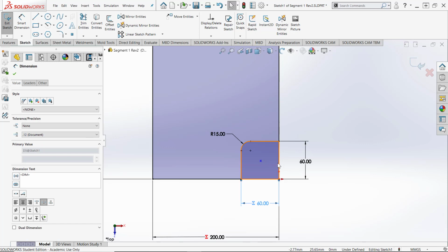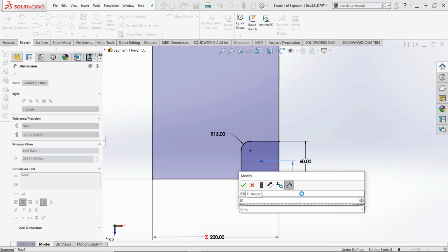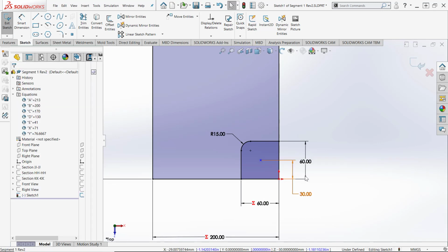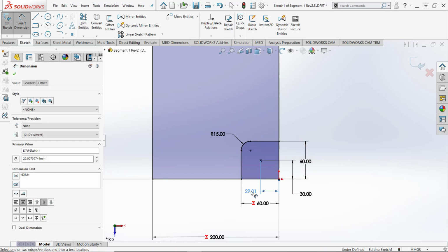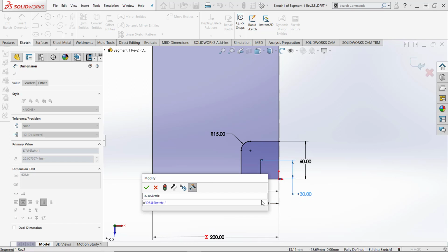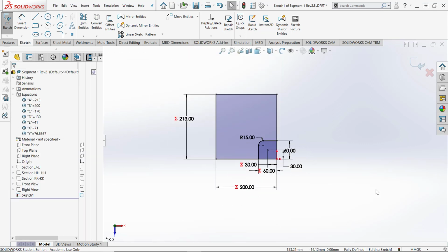And there's other ways I could constrain this, but I'm going to put in dimensions as was shown on the practice. Sometimes if they show a dimension, it might be because they are going to have you edit that dimension, versus if you put in a constraint equal, then you wouldn't need to edit that. So I'm going to go ahead and put this in. They did it as dimensions on the practice, but I'm going to make it equal to this dimension, understanding that if the test asks you to make those something other than equal, you have to be prepared to change that dimension.